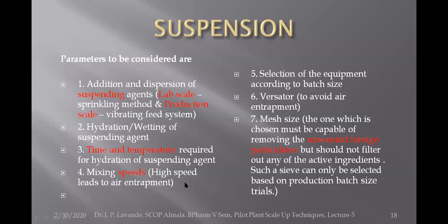Mixing speed: high speed leads to air entrapment. I already explained this, because the air entrapment may lead to bubble formation, and if air gets entrapped, the oxygen from the air may react with the product and affect its stability in the form of oxidation. Let's say it is more prominent in case of oil containing preparations.